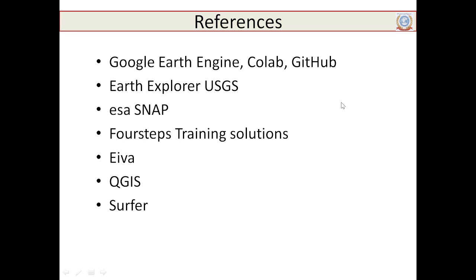And the actual real world bathymetry data collection I mentioned was carried out using HYPACK as well as IVA software. We used HYPACK initially. In this particular study, I used software called IVA, which was used to log the GPS and echo sounder data, as explained in this presentation.